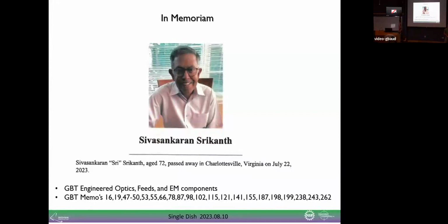That's one of the challenges of cryogenic receiver design, to transition from that 15 Kelvin to room temperature. All these receivers have really two stages, a 15 Kelvin and a 50 Kelvin.